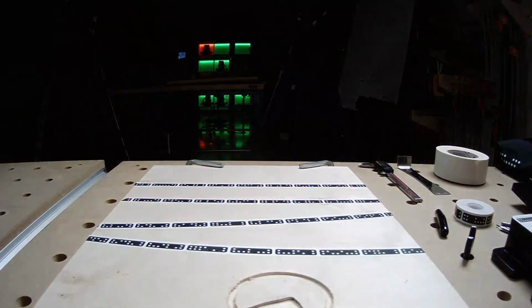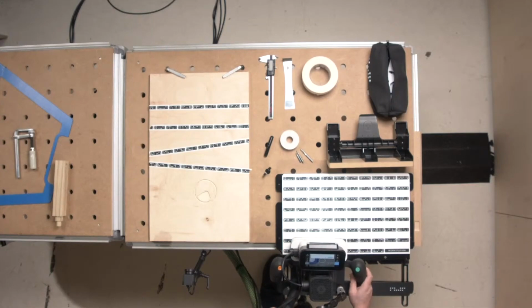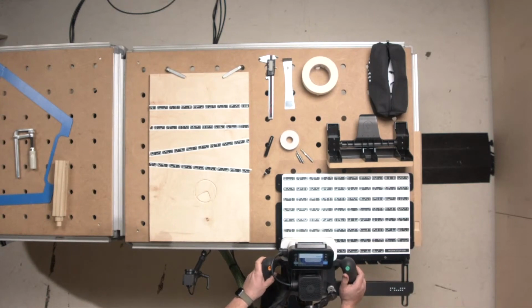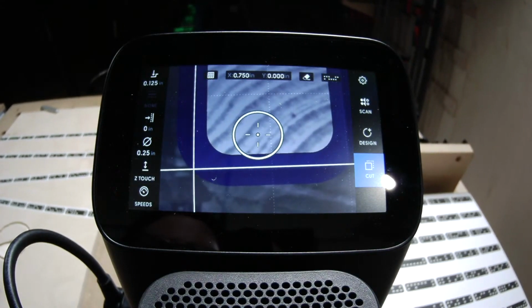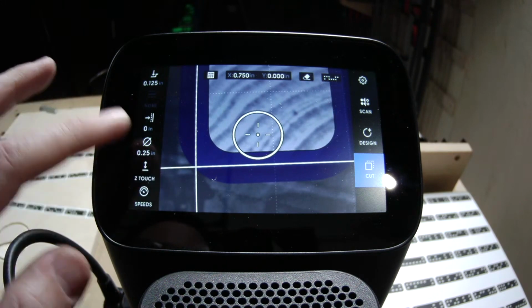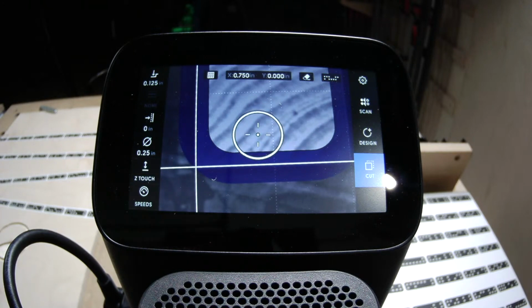And so in the case of the workstation over here, the support bar is going to act as that contact point. So we go back to my top view, maybe Eric. You can see now Workstation's relatively in alignment with the support bar, and I can line up with what I see now is the top of my tenon, and if I go to Z-Touch, it's going to be successful. That's because I have something to touch off on, the top of my tenon, and the bit is aimed somewhere in that area, and my touch sensor is on the support bar.